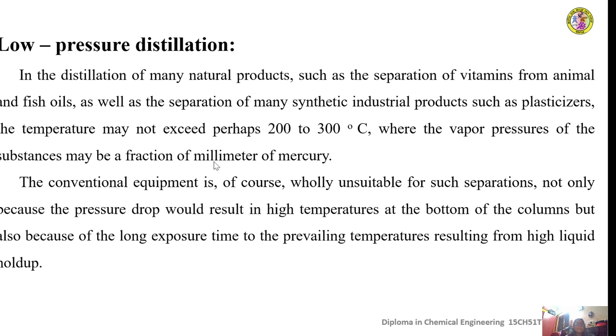So the distillation cannot be carried out in conventional equipment like a tray column, packed column, or any other suitable equipment, so that we already know. Because in that equipment, maintaining a very low pressure drop would result in very high temperatures being created at the bottom of the columns. That is a concern, and also these conventional equipments will expose the material for a very long time to the prevailing temperatures in the distillation column due to high liquid holdup inside the column. So these are the problems with the ordinary distillation method when you have to separate the products that are highly heat sensitive ones.